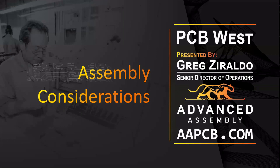Assembly is the process of actually populating PCBs with your parts. This is referred to as populating, stuffing, assembling. It's got a multitude of different terms for it. Heavy copper PCBs, especially RoHS compliant PCBs, can be difficult to assemble due to the solder temperature required.